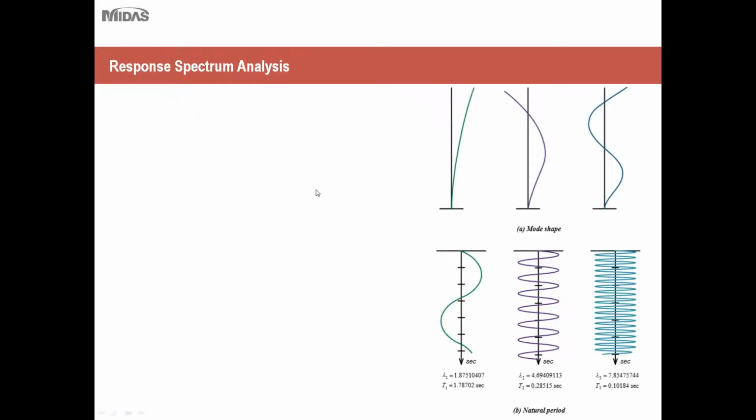First, let's discuss response spectrum analysis. Response spectrum analysis is required by many building codes, and it's used for everything except very simple or very complex structures. Very simple structures would include one-story buildings or very small warehouses, which typically use a simplified seismic analysis method. Complex structures include very large warehouses, high-rise buildings, and very large-scale projects. Response spectrum analysis is the most widely used form of seismic analysis because it hits that middle ground. It's the most conventional analysis type used.